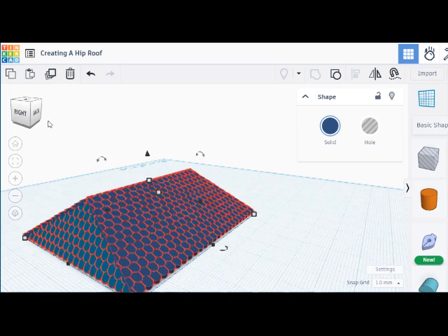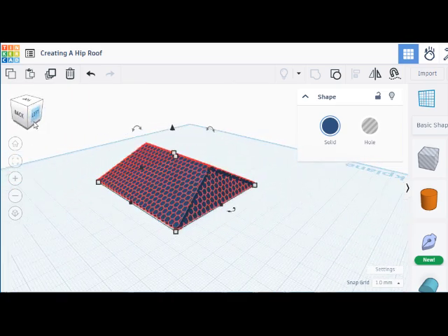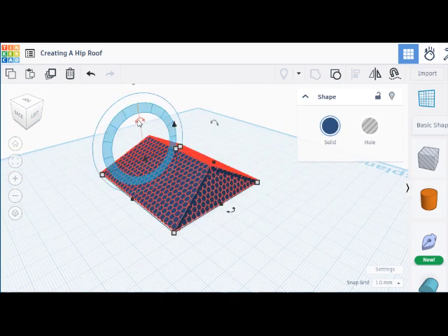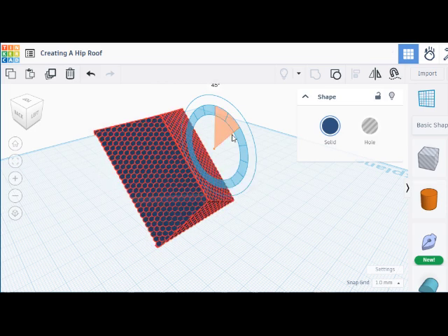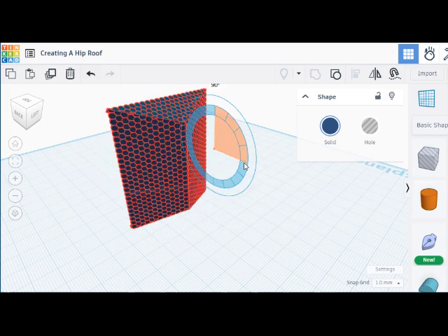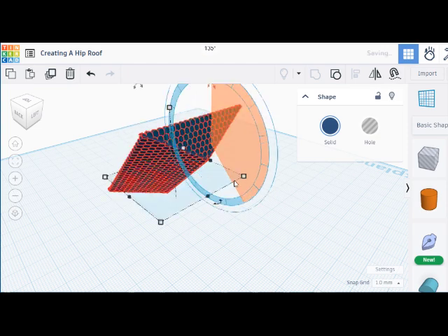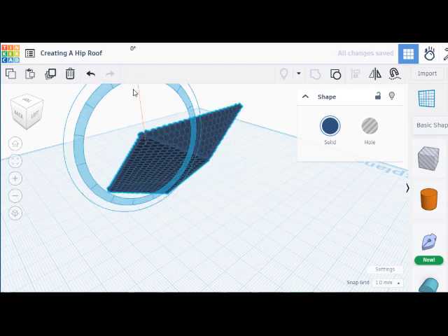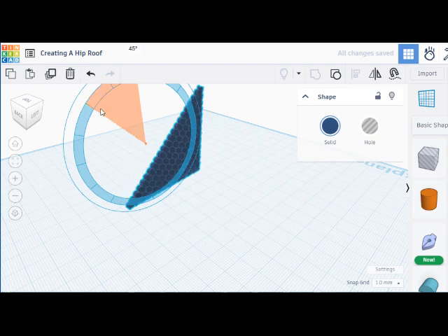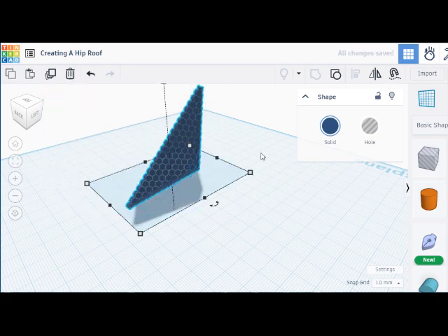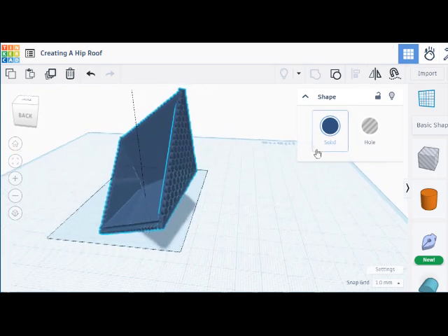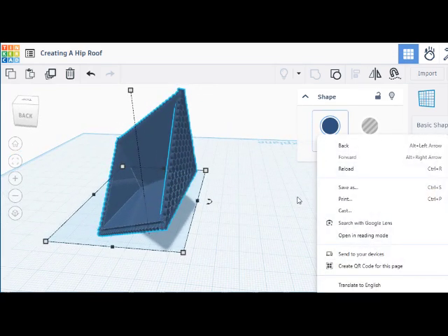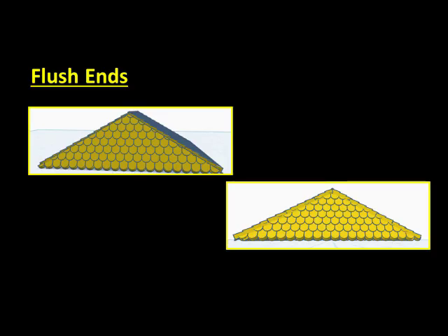Before printing, I like to rotate the combined parts 45 degrees towards its back and 45 degrees clockwise so that it is standing on a corner. I then export it as an STL file and import it into my slicer, where I print it using slicer-generated supports. As soon as possible after the print is done, remove the supports before they harden to the roof. For me, even though removing the supports can be a bit challenging, printing the roof this way gave me the cleanest print.